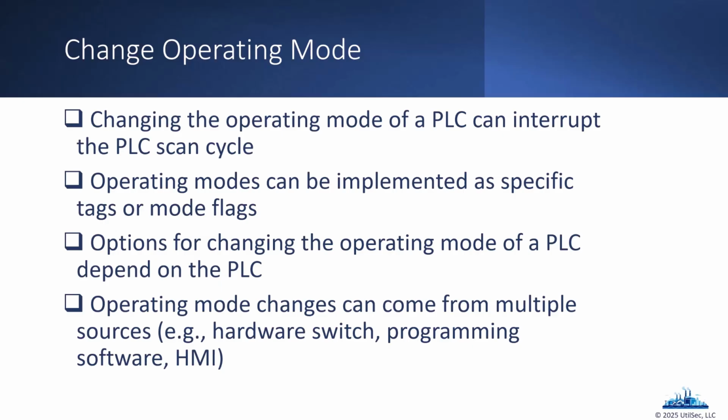Or what if I have the ability to take a PLC from run mode and put it in program mode, so I can put a different version of firmware on the PLC, maybe one that has a malicious component to it? So it is important. A lot of people blow off the operating or operational mode of controllers. But that's why it's important to watch all of your controllers and PLCs to make sure that they're in run mode. And if you ever see them come out of run mode, you investigate right away to see what's actually happening.